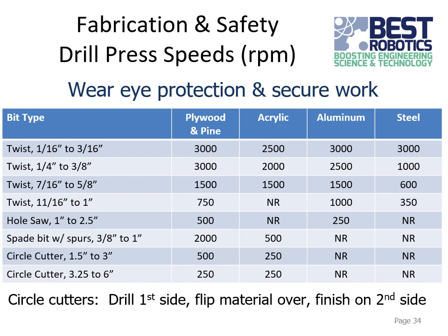With aluminum, you can get away with not using it because it's pretty soft, but a lot of times it's a good idea to use it anyway because it'll make your drill bits last longer. For stuff like that, just ask your mentor what kind of stuff you guys do with that, and they should be able to help you.